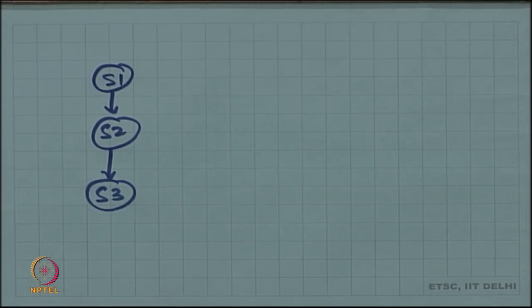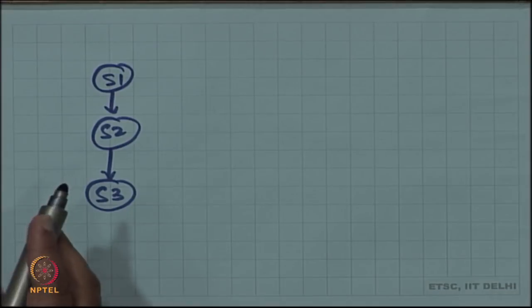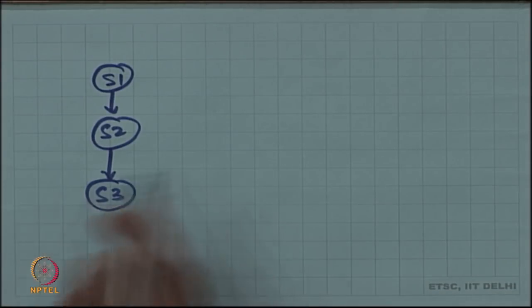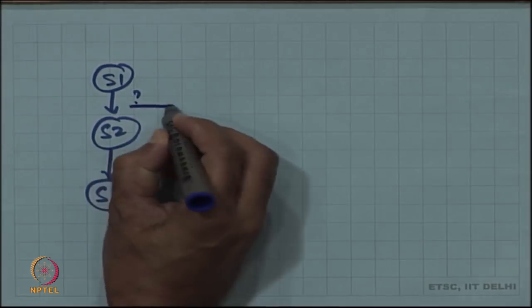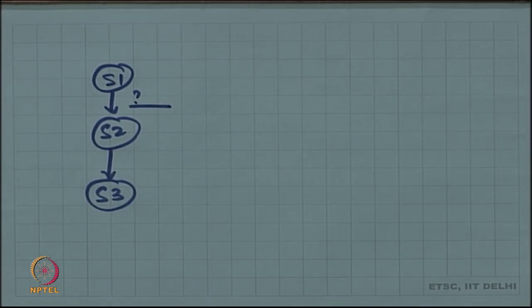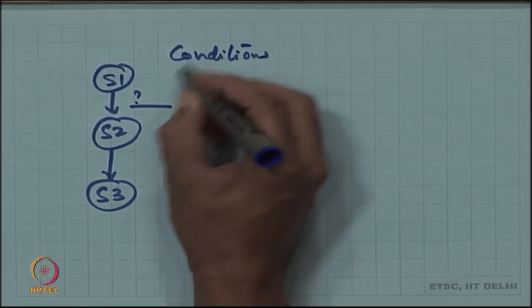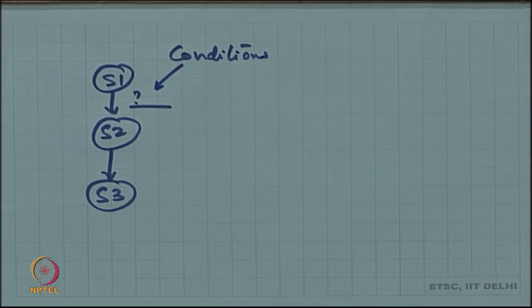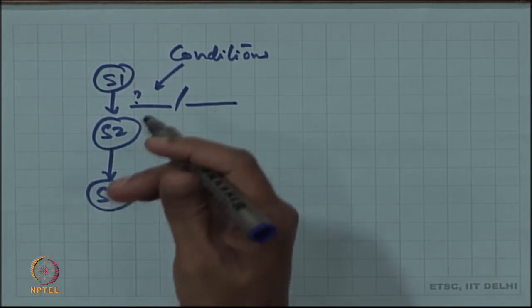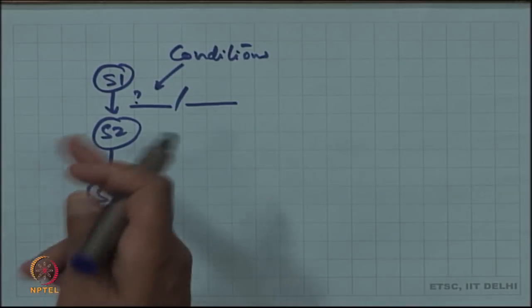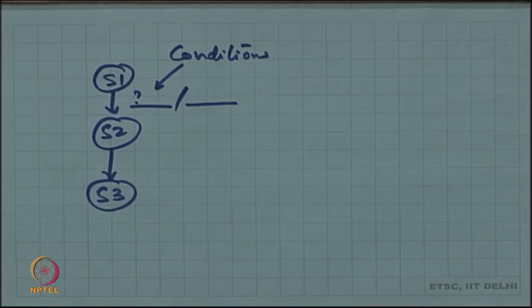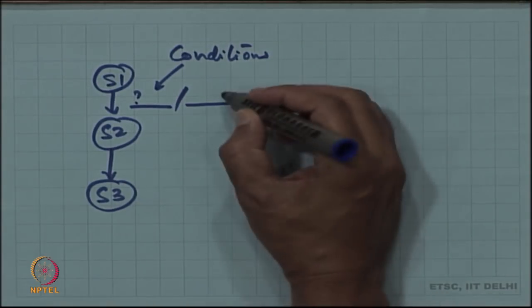What else is there in the FSM? You have states, you have these transitions, you have the conditions. So, I need to specify these conditions, and there are actions. What would the actions be for the FSM? I need those conditions, but there are also actions. I can associate actions with the transitions or with the states themselves, depending on whether I choose a Mealy style machine or a Moore style machine. So, there are actions here, right.